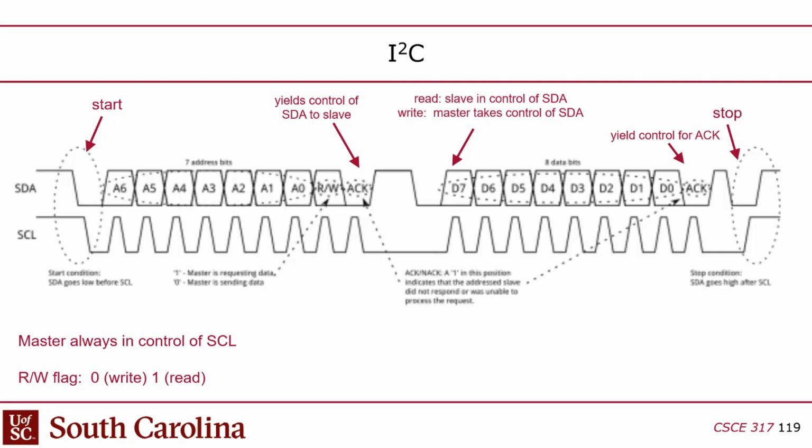In this case, it's a start signal. The start signal is defined as pulling the data low while the clock is still high, right? That is a signal that I'm starting. That's basically an arbitration signal. That means that I want to take mastership of the bus, so I'm going to do something unusual, which is to change the data when the clock is still high. Then, of course, after the data goes low, you also then drop the clock as well, right?